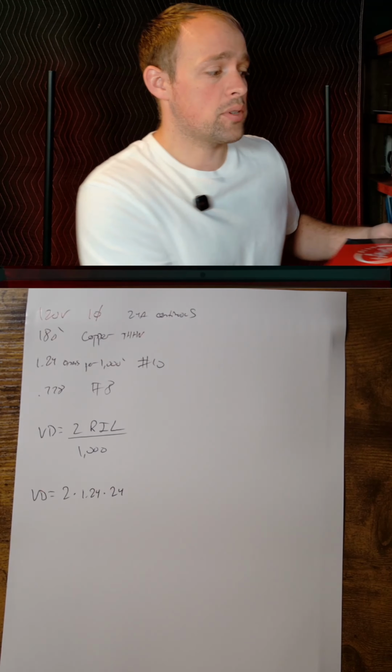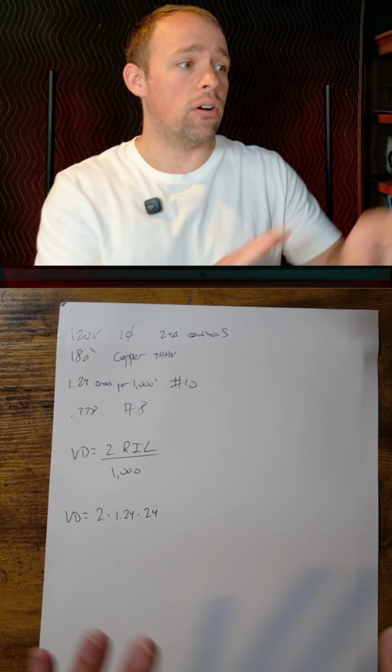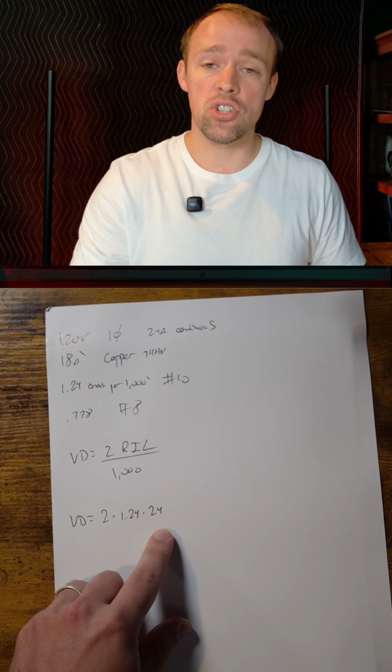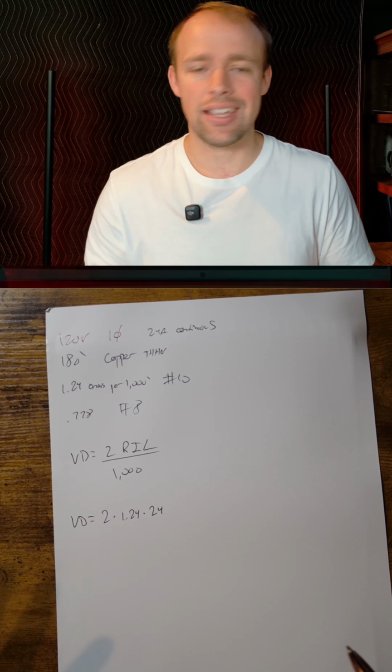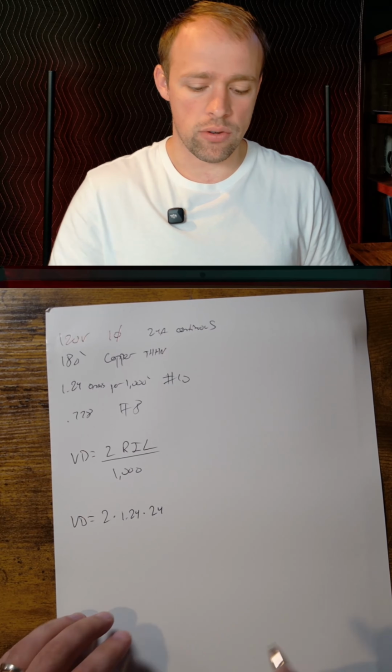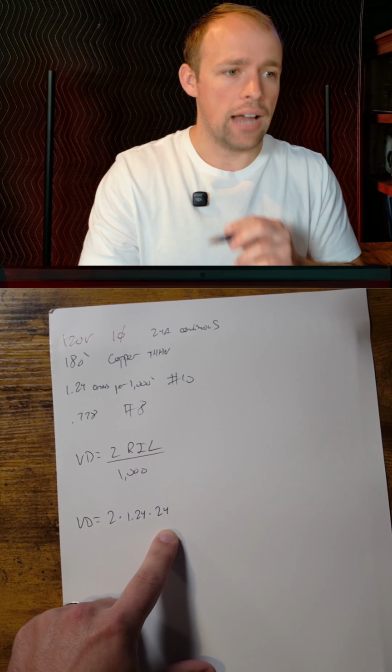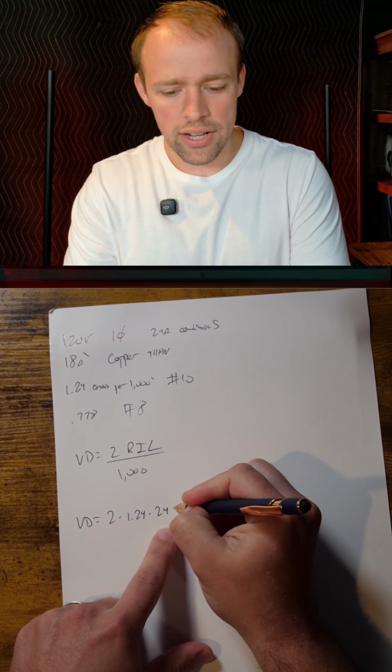So I don't think we need to do the 125% because we're not sizing the conductors right now. The question already did that. We are using the amperage given to us to calculate the voltage drop, not to calculate the branch circuit conductor sizes, okay? So I'm sticking with 24. Let's see if ChatGPT recognizes that. It might not, okay? And then the length, what did it say?